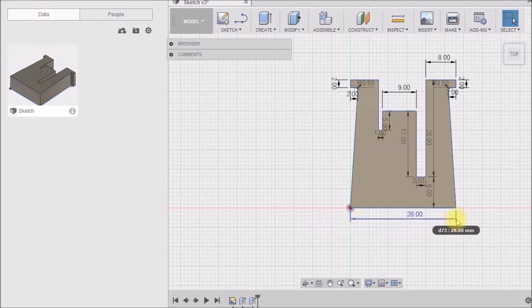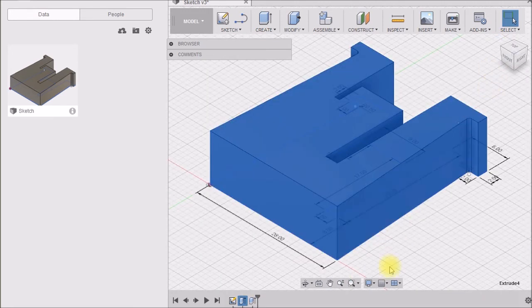If you want things to be constrained, make them 90 degrees and vertical and horizontal. But if you don't want them constrained, purposely make them not perpendicular, because getting rid of those constraints is pretty hard to do. Here I added my extrusion height, which I made 10 millimeters here. And then I also added a little fillet in here to make the print a little bit stronger.